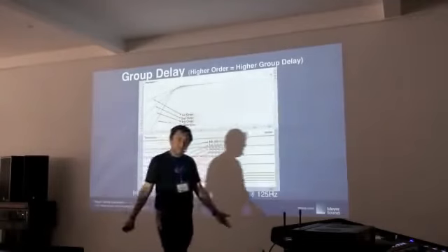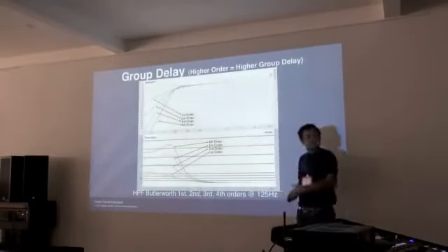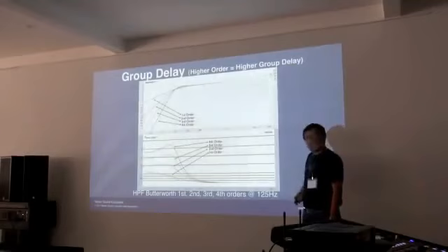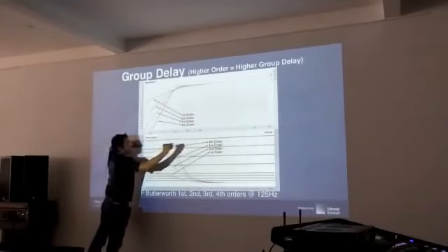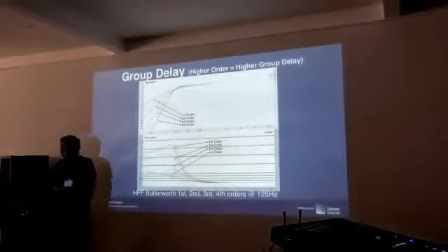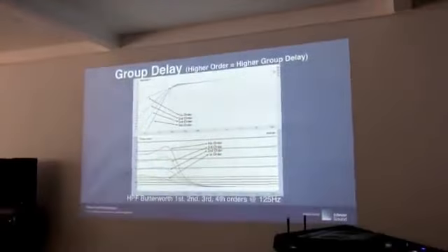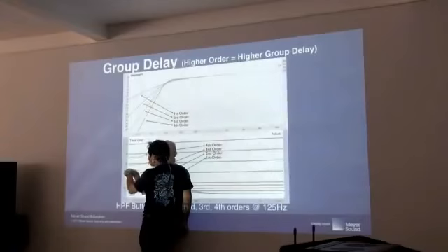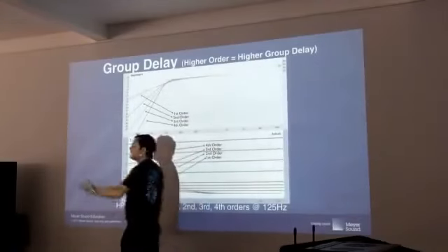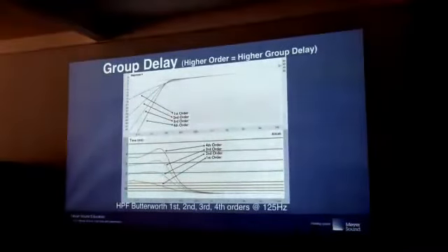Suppose that you are using FIR filter at 125 Hz cutoff, fourth order. FIR filter will delay 4.3 milliseconds all the frequencies. This is called latency. So if the latency of the processor is 1.5 milliseconds, after the FIR filter it can become 5.8 milliseconds. That is what the FIR processor is doing.